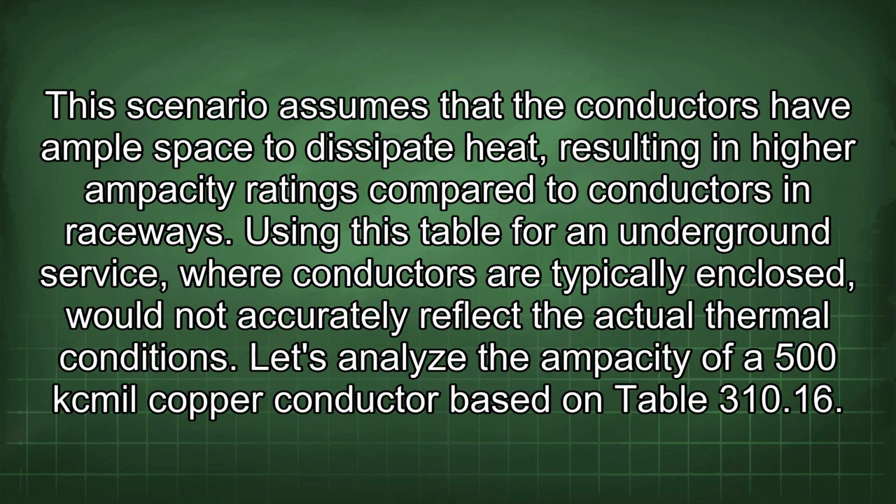This scenario assumes that the conductors have ample space to dissipate heat, resulting in higher ampacity ratings compared to conductors in raceways. Using this table for an underground service, where conductors are typically enclosed, would not accurately reflect the actual thermal conditions. Let's analyze the ampacity of a 500 kcmil copper conductor based on Table 310.16.